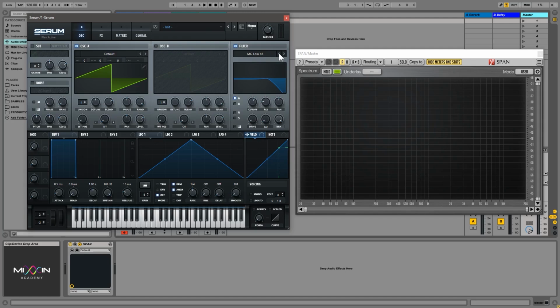Same for this one, 18 decibels per octave, 12 decibels per octave, and 6 decibels per octave. Now these filters are also called 1-pole, 2-pole, 3-pole, and 4-pole filters, meaning that 1 pole is that 6 dB attenuation per octave. We will encounter these in different synthesizers, so it's just different names to the same thing.